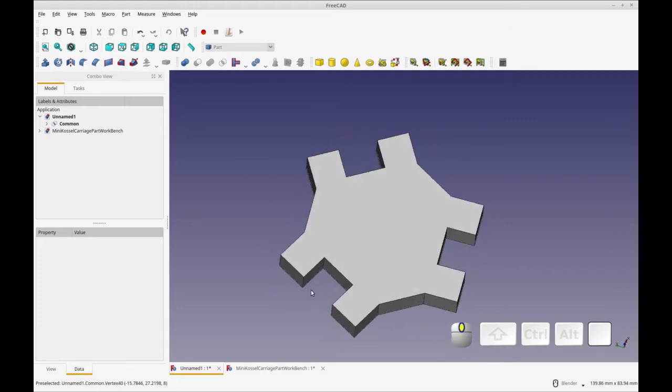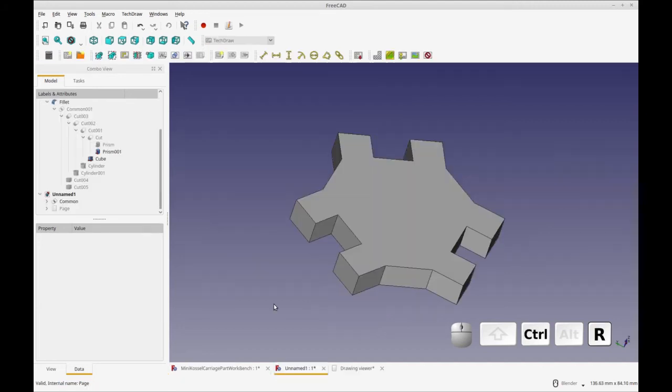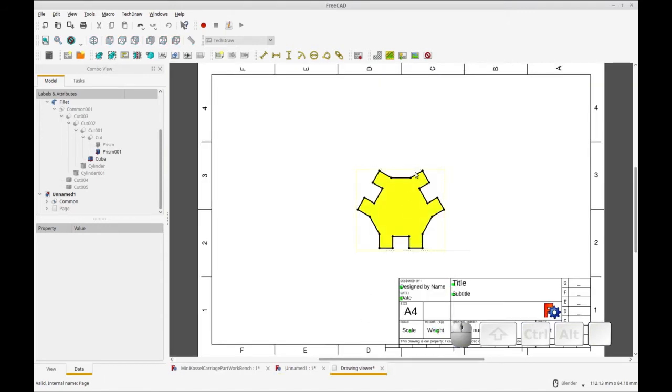Later on, we'll be adding standoffs for the rod arms, cutouts for the nut access. We'll be rounding off these edges. We'll add a polar array of through holes for mounting the hot end, and we'll be adding a cutout for the hot end. So at this point, I want to check my measurements to make sure I've got everything right. So I'm going to go over to Drawing Viewer, where I've placed a sketch of my object, and I'm going to make some measurements.